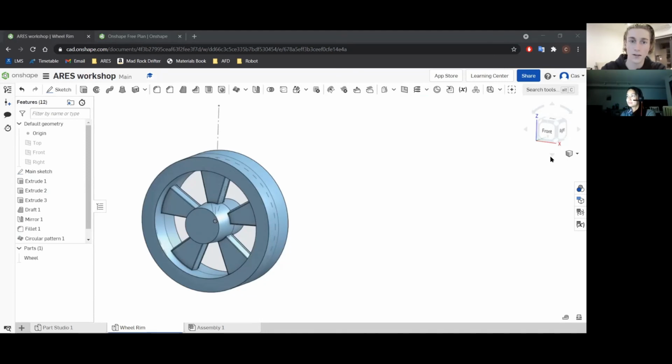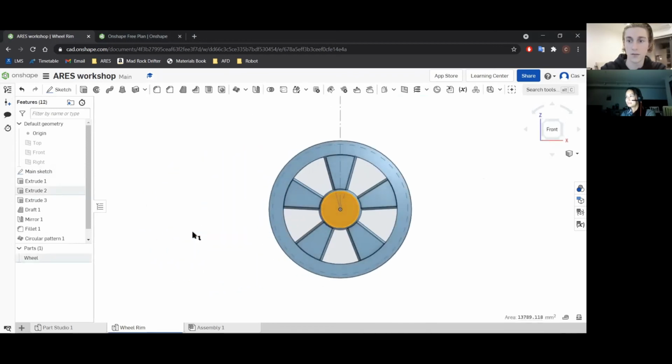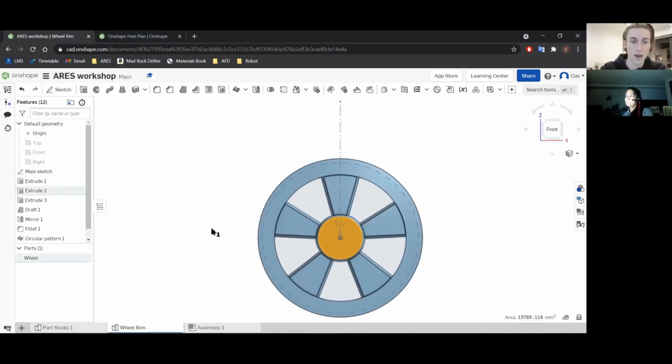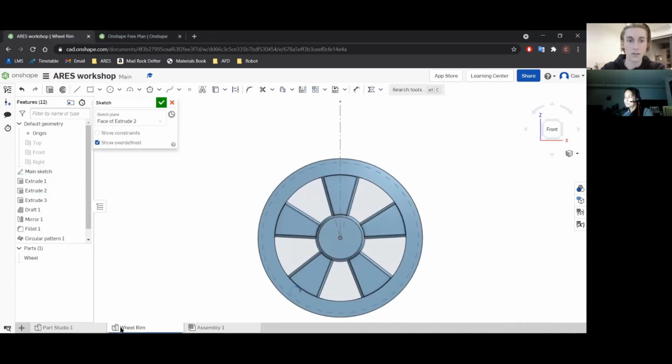Next, we're going to create some bolts into the middle of the wheel. So we're just going to create a new sketch and do a bit of geometry. It'll be a 35 and a 90mm circle. So let's select this circle, press N to go normal to it, and Shift S to create a new sketch.